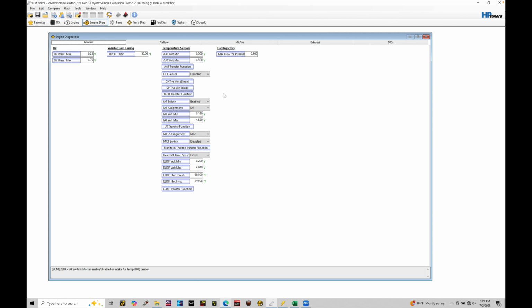Taking a look, there's also a fuel injector max flow DTC that we can change. P0087/88 test. This is going to be a normalized injector flow. You could change this value if you're running into problems triggering your max flow through the injectors. You could raise this up to 0.95 or 1.0. That's going to be for a highly modified, higher power Mustang application or F-150 application. We typically don't change this, so we'll just leave that alone.